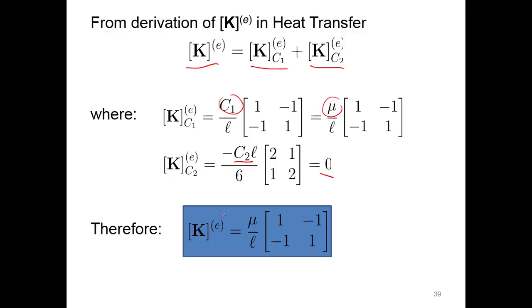All right, so the stiffness matrix that we have here is the viscosity over the length of our element, multiplied times our stiffness matrix that's been developed there. That's our flow resistance matrix. This was kind of its conductance before. In this case, it's the flow or the viscous effects here.